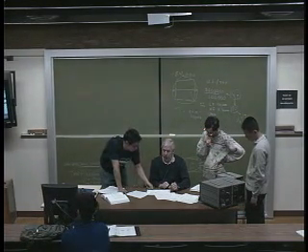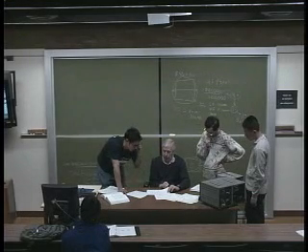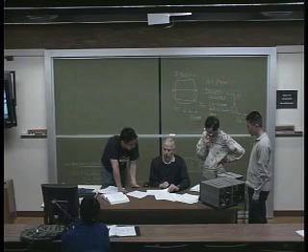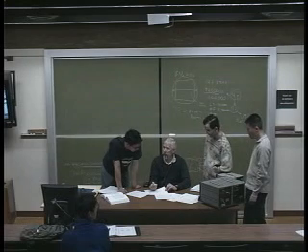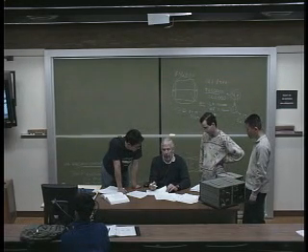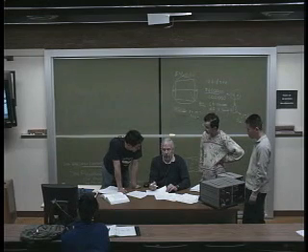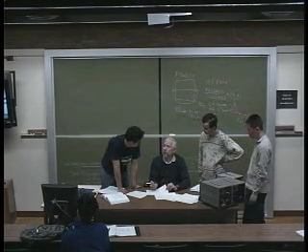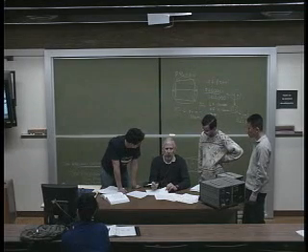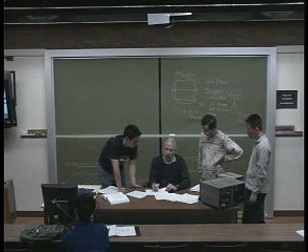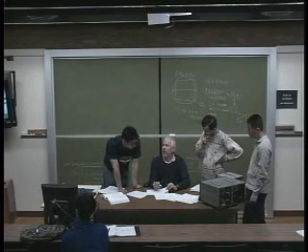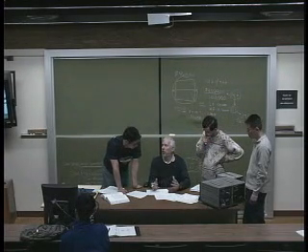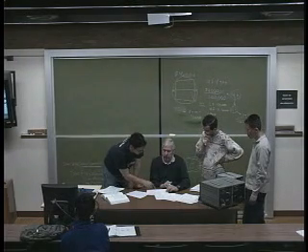Like you said, it moves it this way with less, and it moves it this way with more. How does it move it with more? What's the equation? Well, it's this sigma, the real part of the pole, gets larger. Okay, phase margin is directly related to the real part of the pole. What's the equation? It's not that straightforward. You might be able to work it out if you want to. For a single pole, or maybe take 2 poles, figure it out, and you may get some expression.